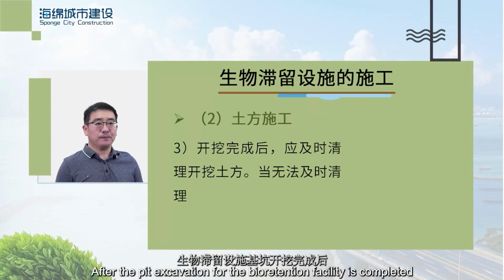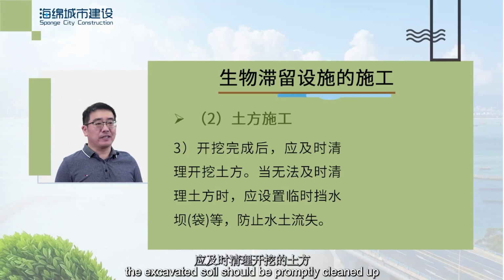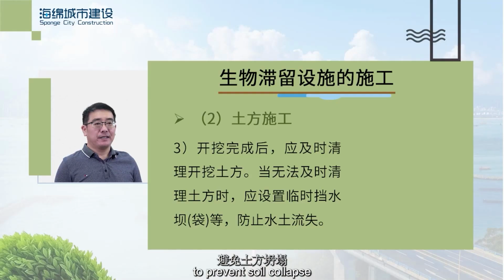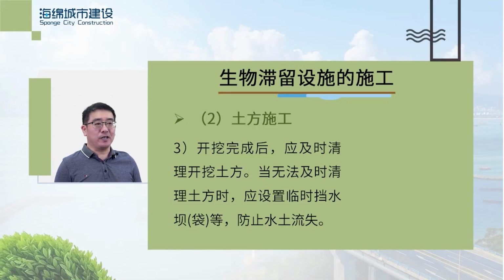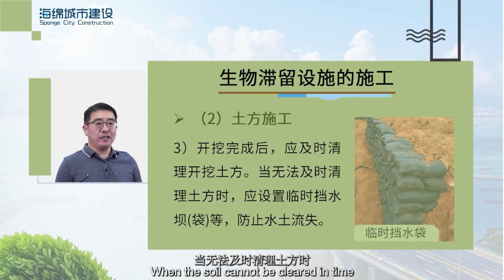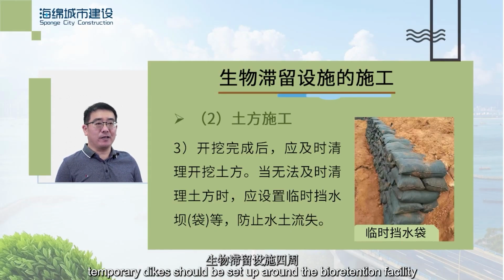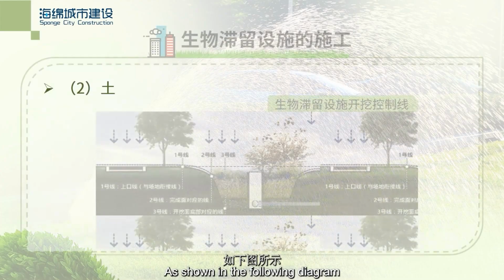After the pit excavation for the bioretention facility is completed, the excavated soil should be promptly cleaned up to prevent soil collapse, which could negatively affect the depth and performance of the bioretention facility. When the soil cannot be cleared in time, temporary dikes should be set up around the bioretention facility. And at the reserve water inlet, temporary dikes should be installed to prevent soil erosion, as shown in the following